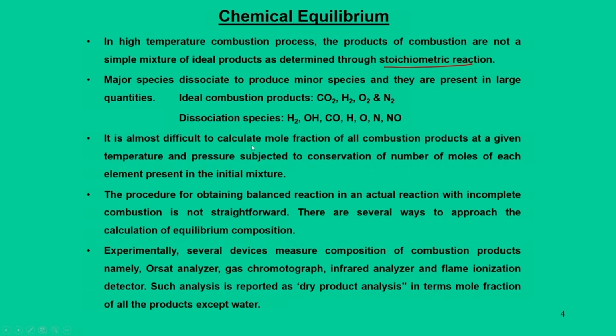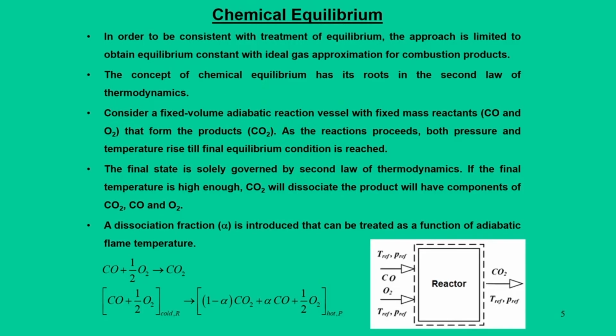It is almost difficult to calculate the fraction of all these combustion products at a given temperature and pressure subject to conservation of moles of each element present in the initial mixture. So, the ideal calculation is not straightforward. So, we have to rely on experiments, taking samples of the combustion products and analyzing them, and we can report the composition analysis, and that will tell whether you have achieved the equilibrium or not.